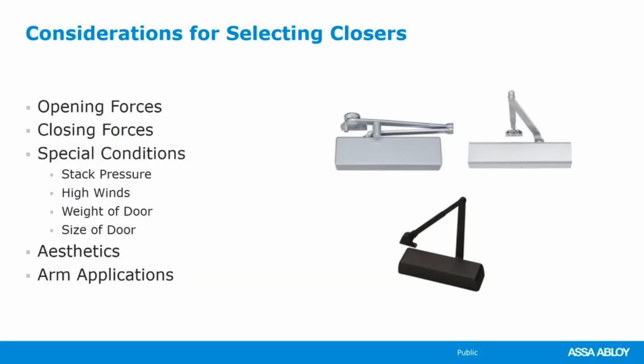So before we go further, let's talk about how a door closer works. And this pertains to every door closer manufacturer. Every door closer manufacturer uses what we call a rack and pinion method, where you have a spindle that attaches to the arm of the closer. As the door opens, the arm moves, turning the spindle, which pushes a piston back and forth. Let's see how that works.